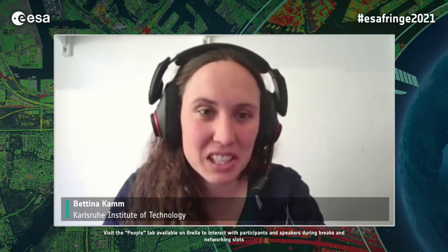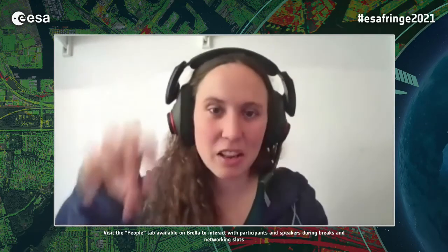Yeah, thanks. I don't know for Bettina if we do have questions. Yes, there's a question asking, aren't you introducing the atmospheric bias by subtracting the ERA5 mean ZWD, zenith delays, I guess, from the PS points? Yeah, so I checked that. I also looked at the difference between my ERA5 zenith wet delays in comparison to the GNSS wet delays, also using the zenith wet delay at the PS point location. And there I didn't have this bias, or I had a much smaller bias, so it's not introduced by the ERA5 data.